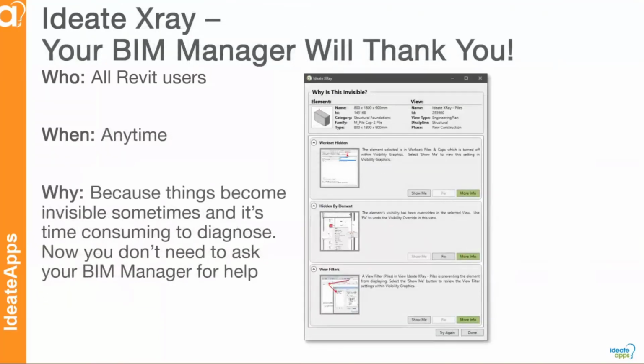And then Ideate X-Ray, this is where I said I was going to focus. There'll be a whole presentation next month, but it allows you to understand why a particular element is not visible in your project. And this can be very frustrating, especially for a BIM manager. One of the designers might say, well, I can't find this, or this grid doesn't display anymore. And so they're running to the BIM manager to try to help them or fix that. Now they can actually have a very easy tool to use to determine why something doesn't display in a particular Revit view.